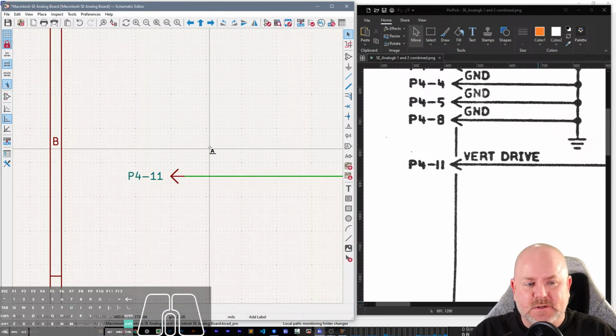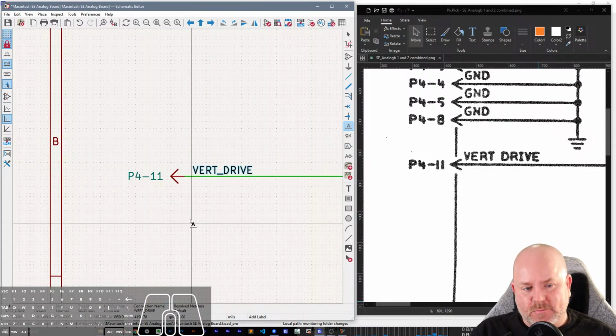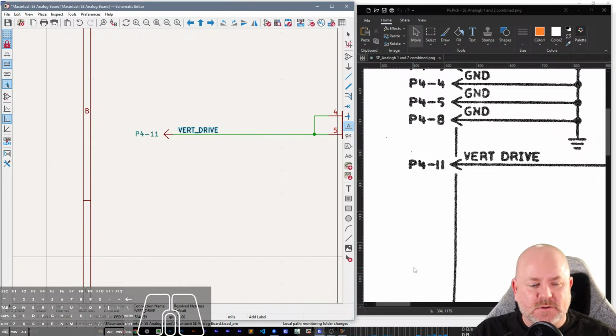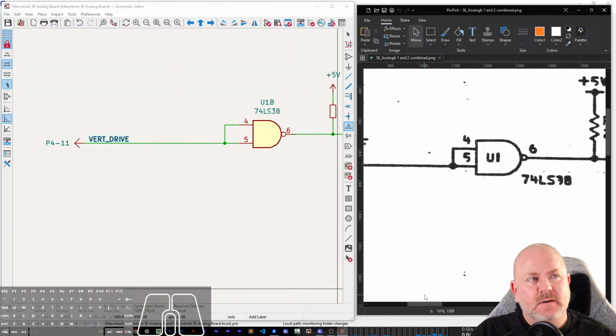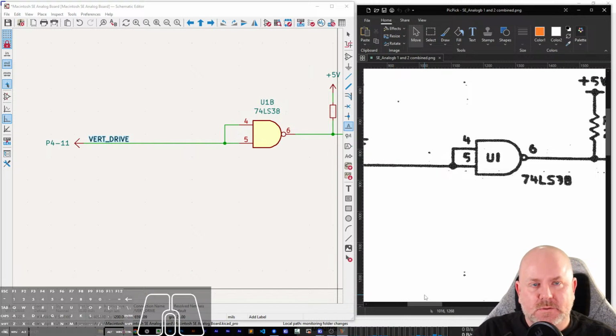It's one of those things where pack and go is the most useful feature, and then there's some ways you can change cross probing. There's also a couple of hotkeys that you can use while you're in PCB, I think it's either T or Shift T. The T isn't like Tom. You hit that, and then you type the designator, so like C11. And then what will happen is wherever your cursor is, C11 will snap to it.